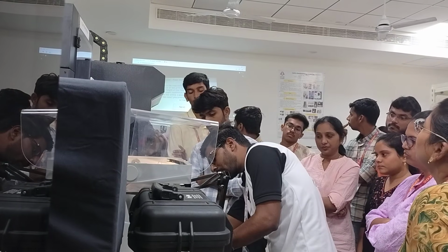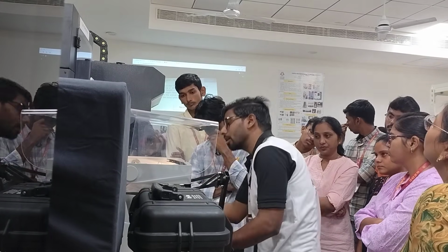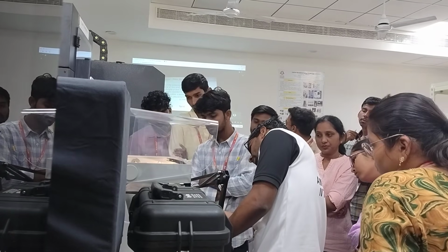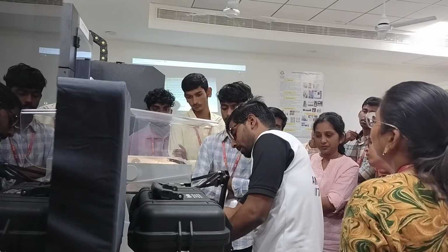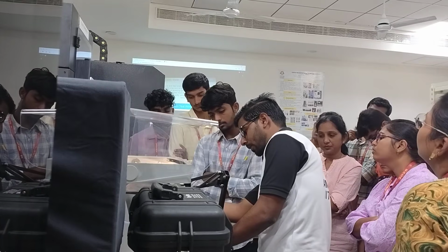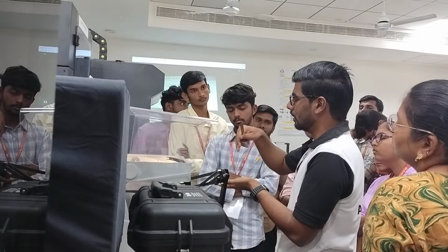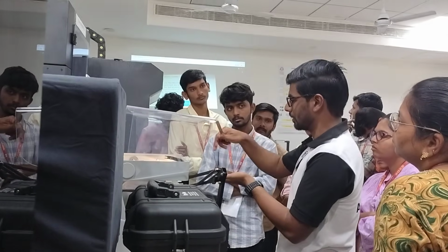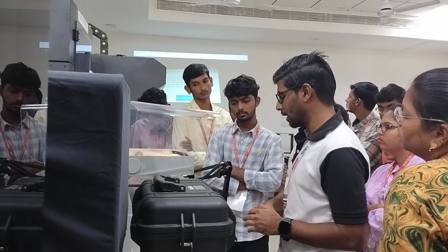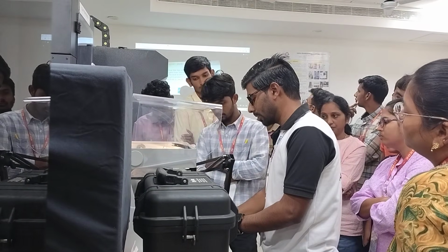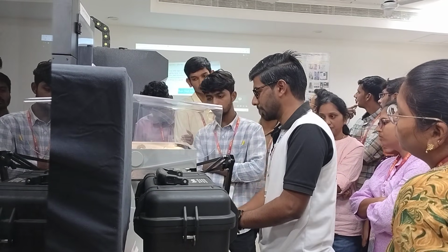Adjust the exposed 2 mm Allen key. There is an Allen key here. Since I have it proper, I don't need to adjust. Same resistance is there. Now since the bed is adjusted, and I have also adjusted the fiber nozzle as well as the plastic nozzle, I can do a test print. So I'll click on test print. It is always advised to do test prints.